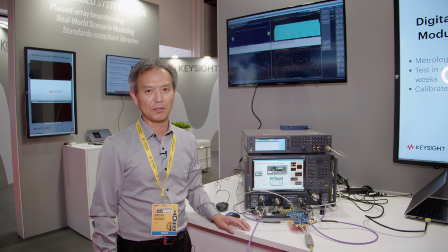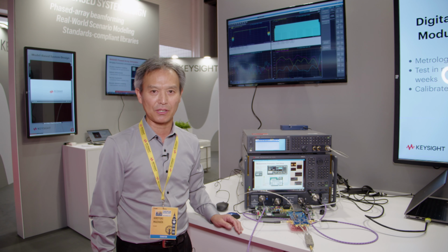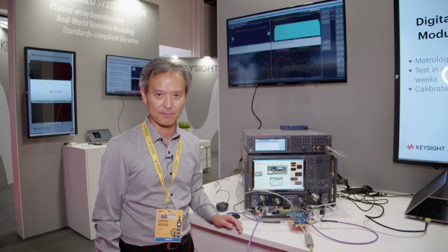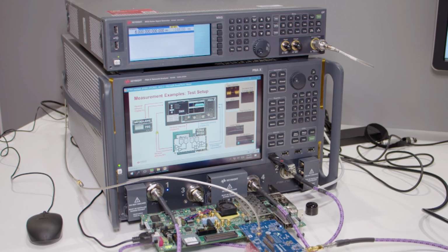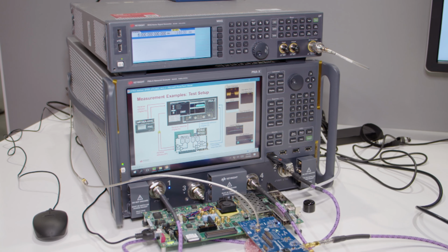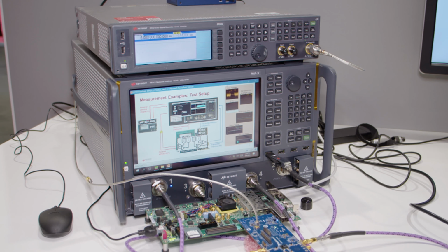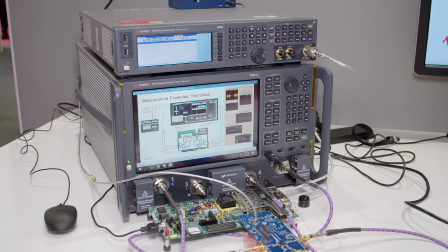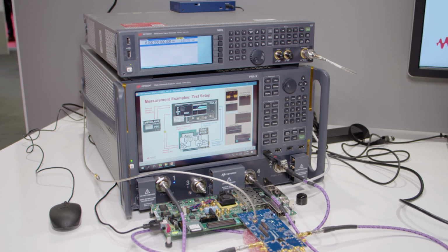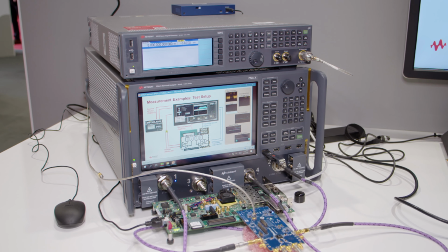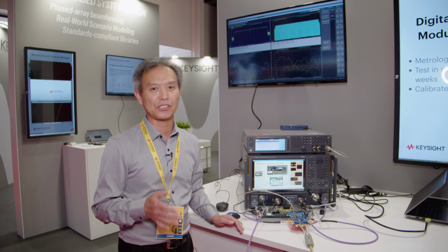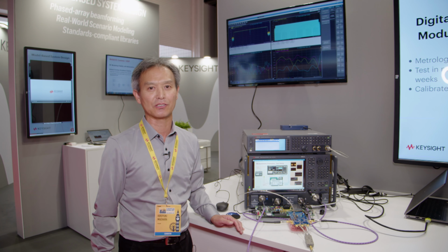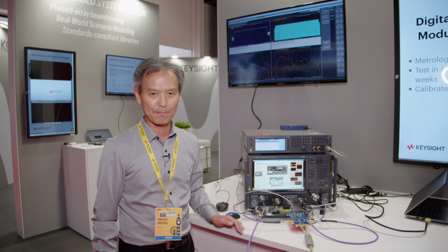A typical example, which we are using for the demonstration, is the transceiver IC. Recent transceiver ICs have much higher sampling rates and wider input bandwidth, digitizing the direct RF signal into digital data. When designers want to characterize RF performance, they have to deal with the digital data, which no longer lets them use the traditional RF-to-RF test instrument to measure the RF performance.